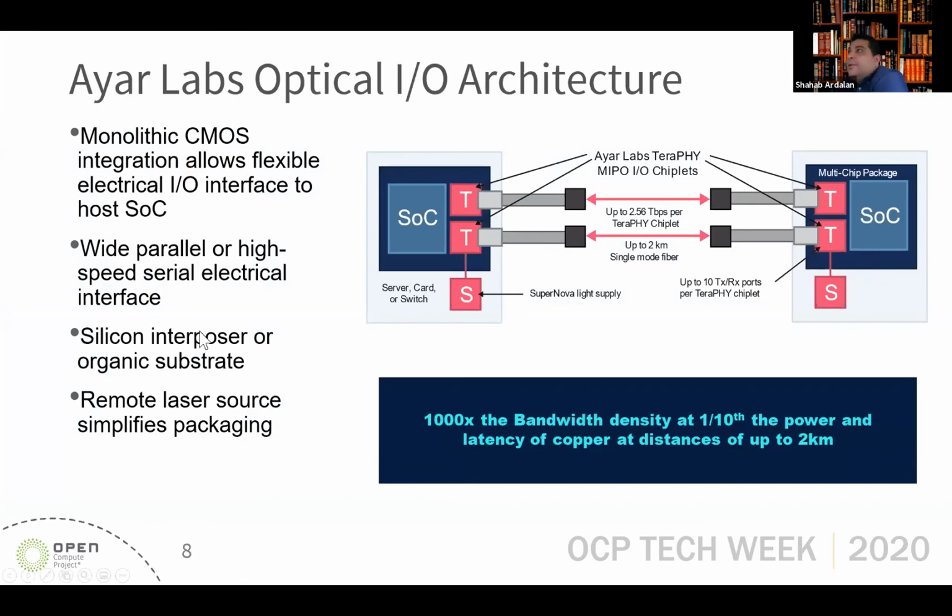This is after developing all those steps. This is what we so far achieved in Ayar Labs. We have a monolithic CMOS integrated silicon photonics, as we call it, TeraPHY, the red one here. The laser source is going to be outside the environment of the chip, which could be on the board. The laser is coming to the TeraPHY. TeraPHY with the SOC, could be ASIC, could be CPU, GPU, anything, is going to get packaged in the 2.5D architecture or EMIB approach, anything, and enables actually the optical communication to the outside. And the fiber is going to come directly actually to the packaged SOC.